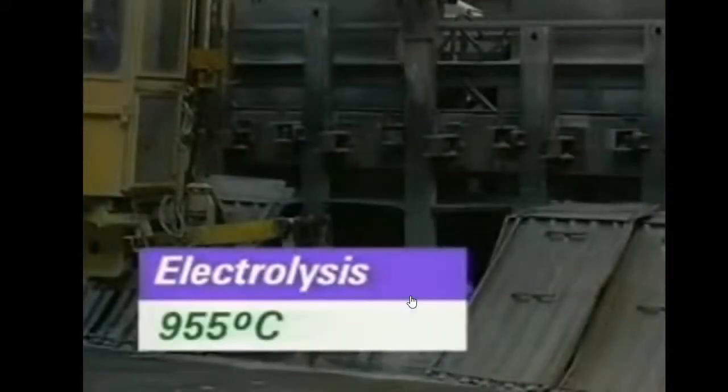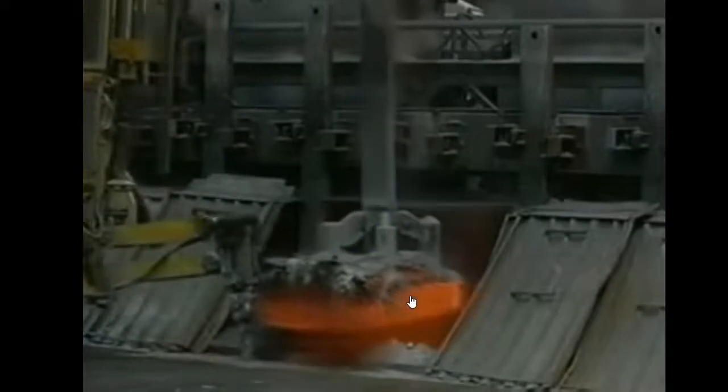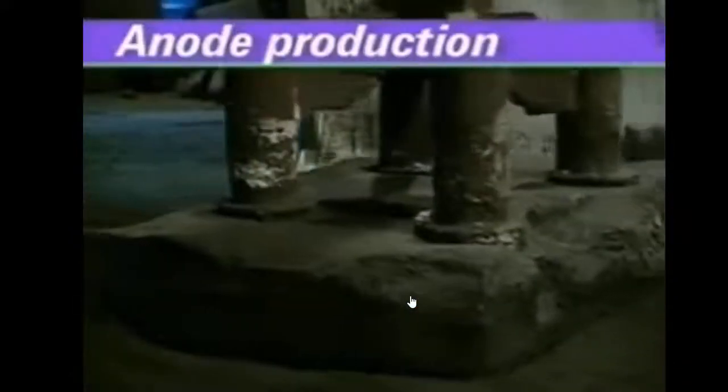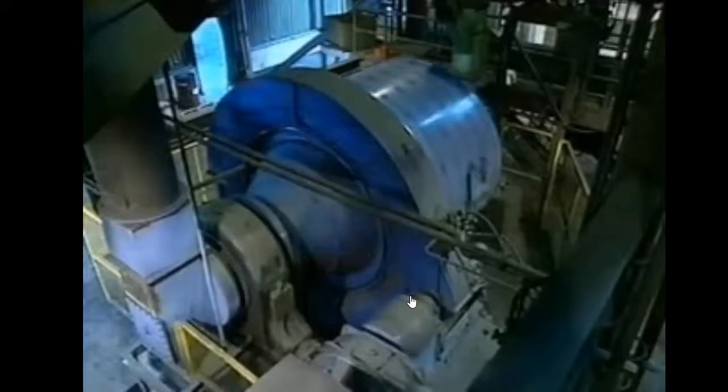The electrolyte is at about 955 degrees Celsius. At this temperature, the carbon anodes gradually burn away in the oxygen from the electrolysis. Eventually, the anodes have to be replaced, and this happens every 28 days or so. The remaining carbon is broken off the old anodes, crushed, mixed with new coke and pitch, and pressed into shape.